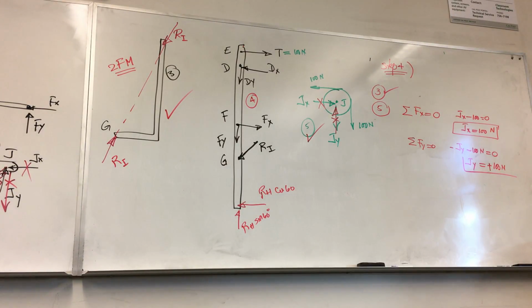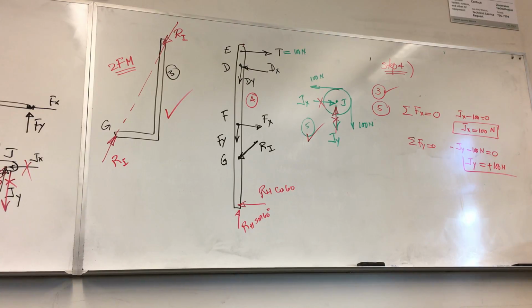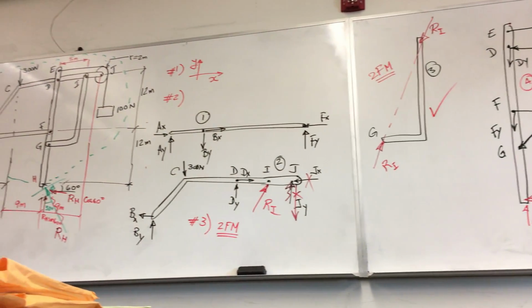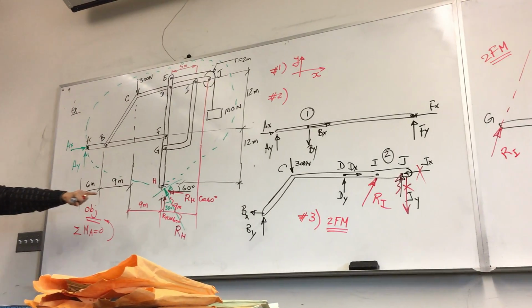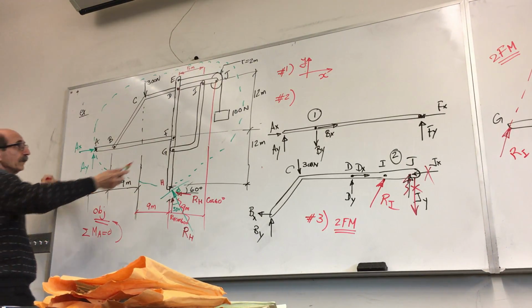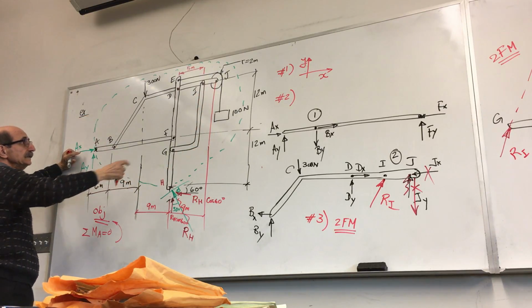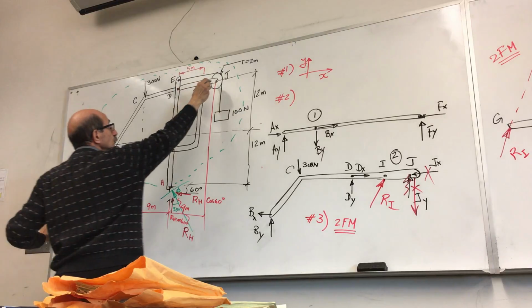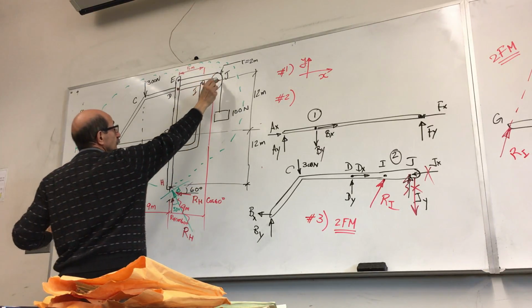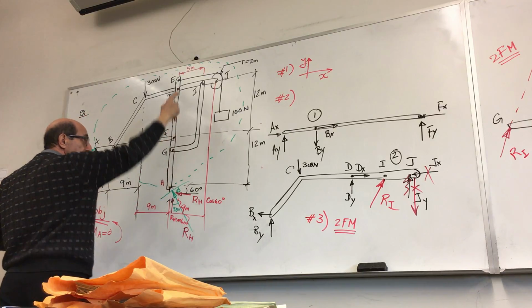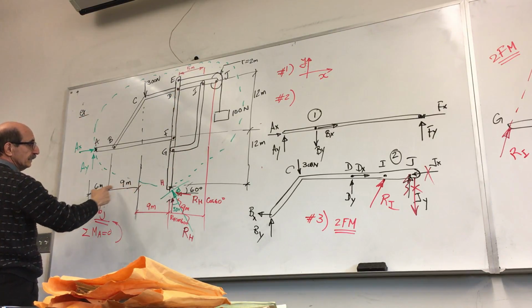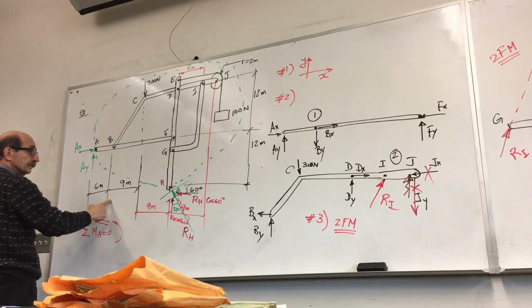So I'm going to come here. And what do I do? I will take summation of moments about A is equal to 0. All those good things we had learned, right? Applying equations of equilibrium still holds. Take summation of moments about 2 unknowns to get rid of them, so I have only 1 unknown left. So let's do that. I have 1 force here. The distance is what? This is 2. This is given as 2, right? This is 9. So 11, and 18 would be what?